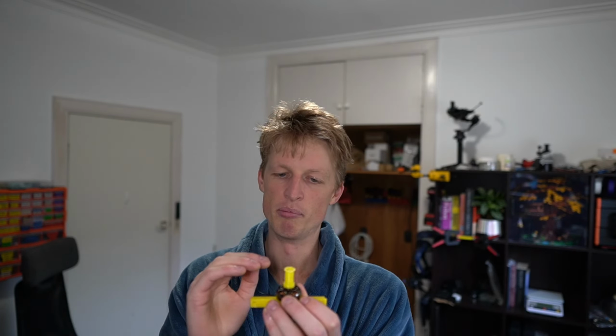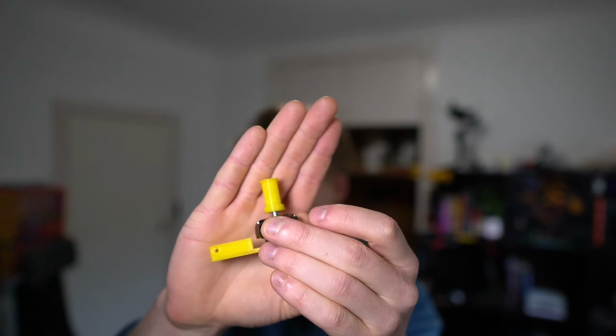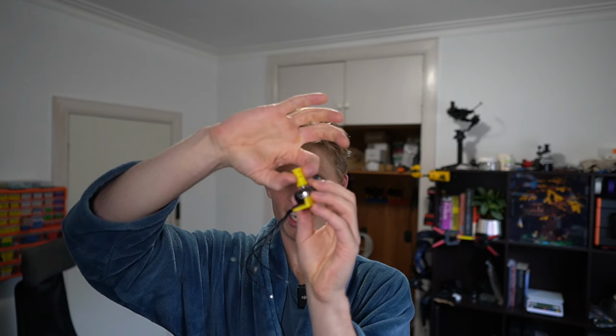and catching, it's better if the spool that the string is wrapping around is quite small. Like this is a 6mm radius, a 12mm diameter spool. And this is very small, which means that if this is on the base and the platform moves over to some wacky angle, the end result is that this will need more string wrapped around it if it is on the base than if it is on the hand. It will have to accommodate more string, which means it will have to be much longer because it's so damn tiny that the string has to wrap around so many times.